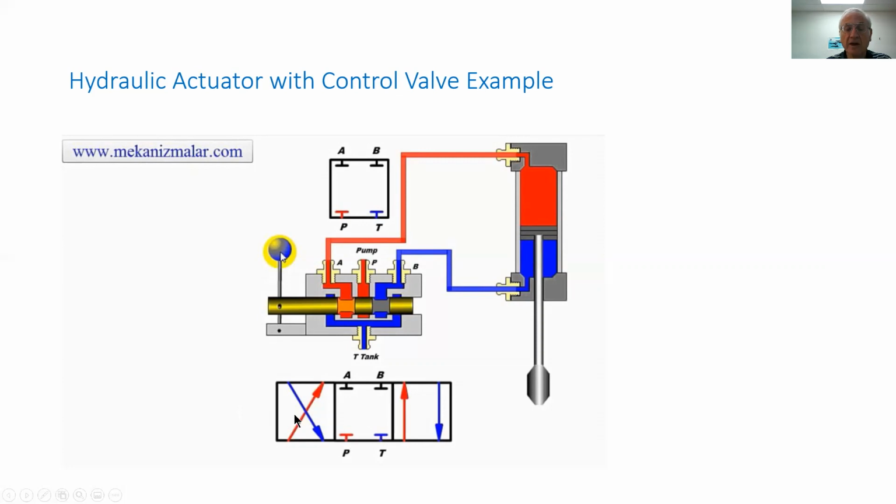We have the possibility of having the system either in idle or in a position like we see on the right-hand side, with the pressure connected to port A, and then the fluid goes into the top of the cylinder and pushes it down. While it pushes it down, the hydraulic fluid is escaping through the bottom section into the tank.